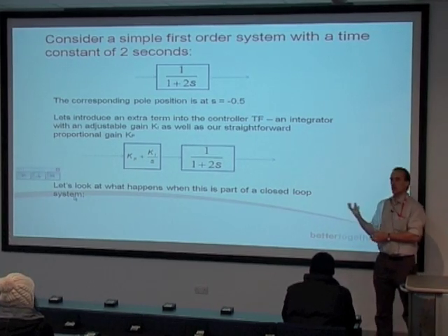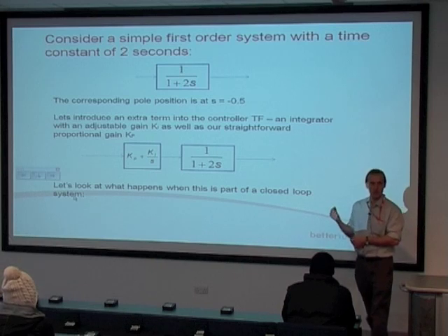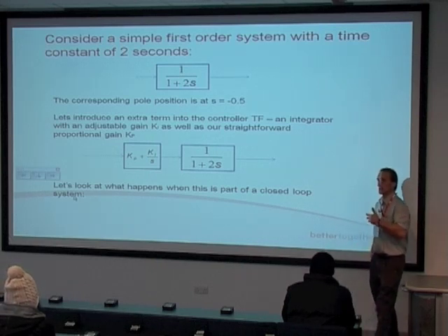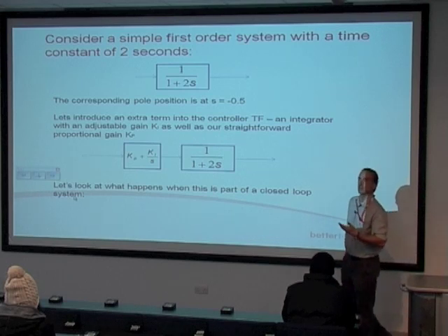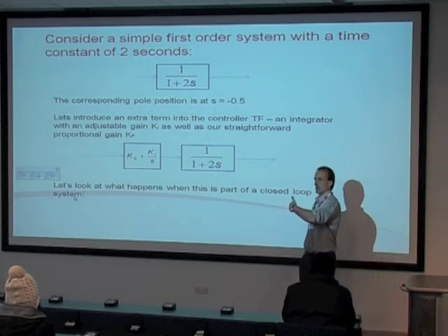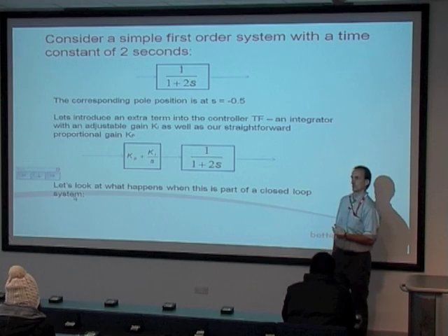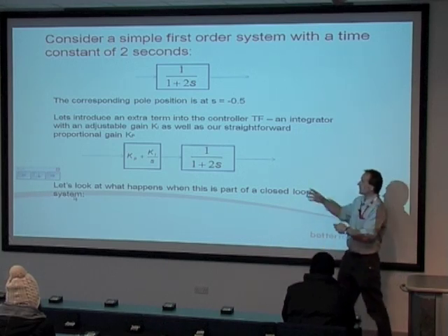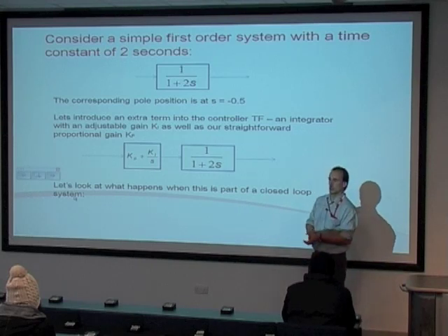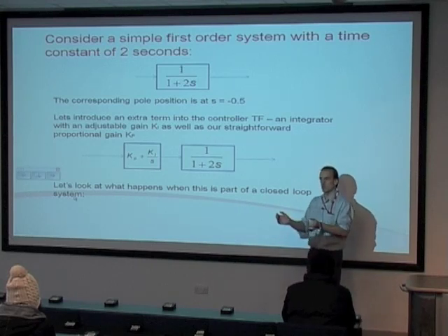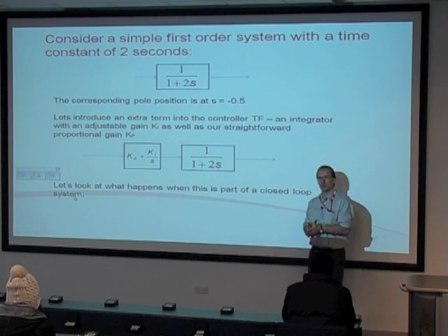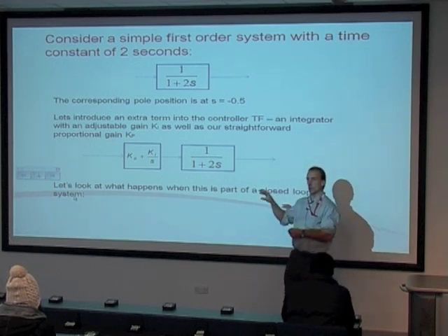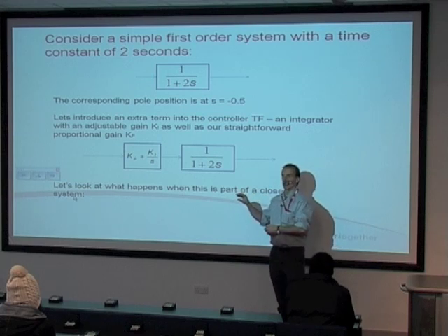And typically, a cruise control is designed to control speed. Okay, so the input variable is a desired speed. Okay, I would like to go at a steady 70 miles an hour. Then the process, the forward path boxes, if you like, are to do with the engine and the transmission and the wind resistance and all the things that govern the dynamics of the car. And the output that we're interested in is, well, what's the actual speed?